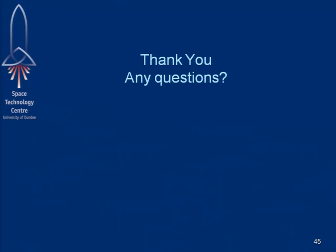Thank you. The other thing there is we can use broadcast codes to do time slot synchronization. So you can either do that directly, so you can have time codes that come in and say synchronize, synchronize, synchronize, or you can do it by sending out a time code which has the time in it, an unsegmented time code, which fits inside a broadcast message. So you can say this is the time, and then you can use a local time counter for doing your time slot synchronization, which is the preferred method. But you can use both.